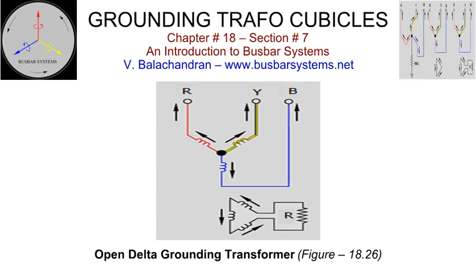The resistor bank can be installed in the middle phase of the surge protection voltage transformer cubicle. The sizing of the transformer and the resistor can be carried out by equating the losses in the resistance to the charging reactive volt-amperes of the capacitance of the ungrounded path.